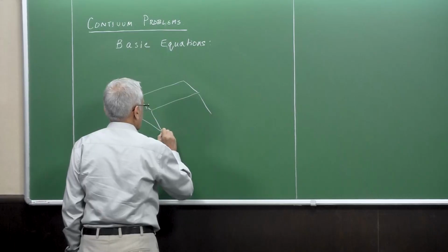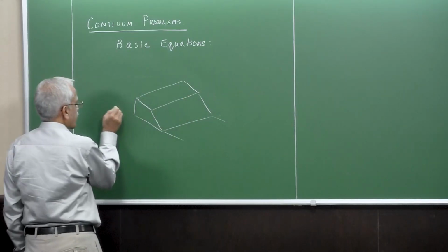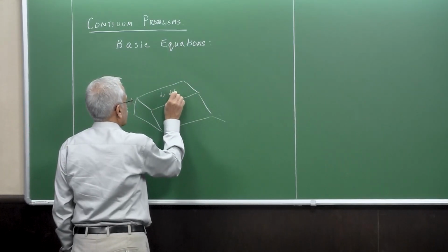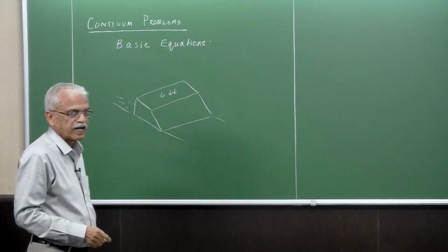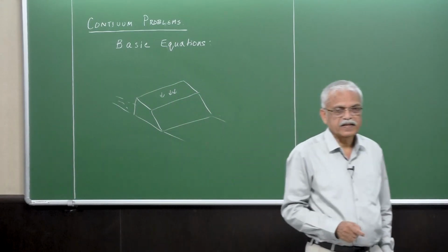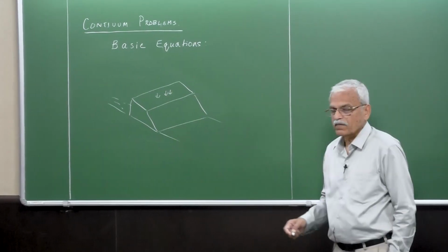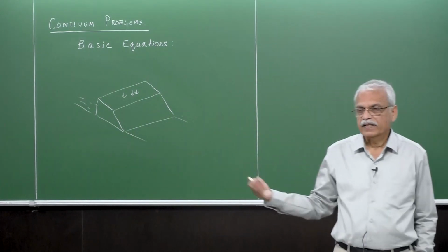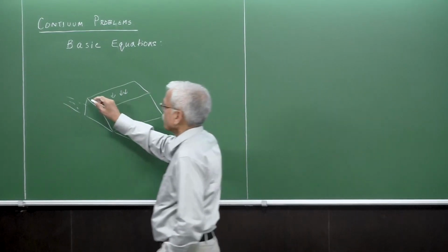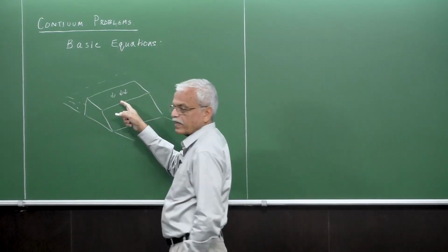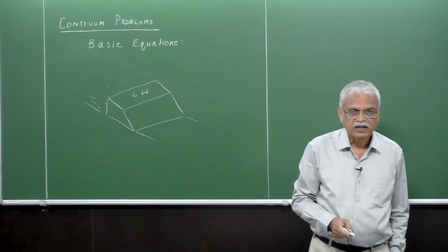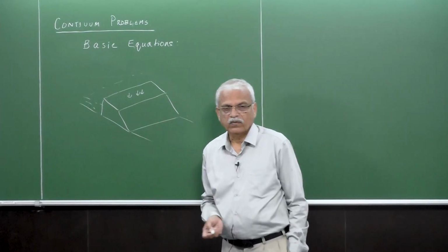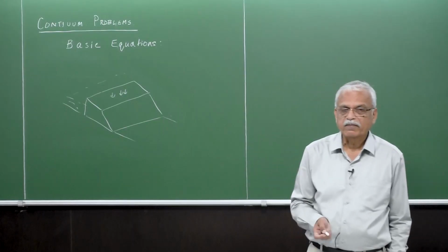typically a dam with some loads here. So this dam is a three-dimensional body, and the matter is continuously distributed over the domain, a three-dimensional domain, which is of our interest. Something like if there is some typical water here on one side, and then there is another load, the traffic load on the dam, and typically how you want to find out the deformations, followed by the stresses and strains, which are of primary importance.